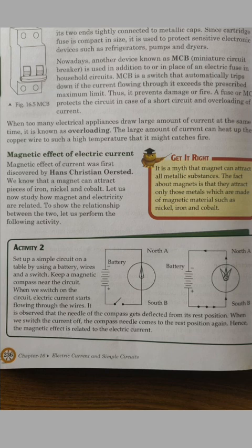Now there are certain terms and definitions, that is overloading and short circuiting. So what is overloading? You might have heard this during the peak summer season, when you turn on all the fans and lights, and your parents or grandparents say, don't use it too much, there is a condition of overload. So overload basically means you are drawing more current, when the load is very heavy; in simple words, multiple appliances are being used at once. Because of that, if more current is drawn, the wire might get too heated up, the plastic coating on the wire will melt, and it might result in short circuiting.